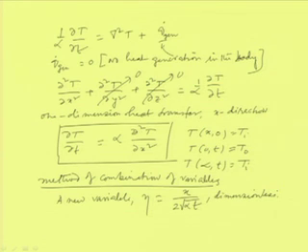Once we have x and t combined into a dimensionless quantity, a new variable, then we will write temperature also in terms of dimensionless variables. We will write first the reduced variables and then dimensionless. So, T will be written as T bar by T O bar, where T bar is equal to T minus T I, and T O bar is equal to T O minus T I. So, this is the way we have now defined two variables, eta and T.